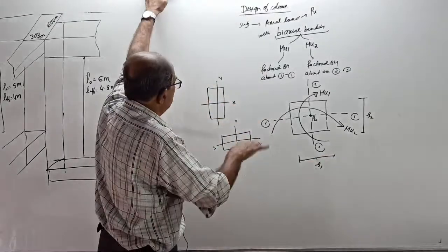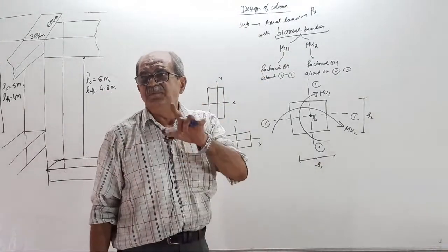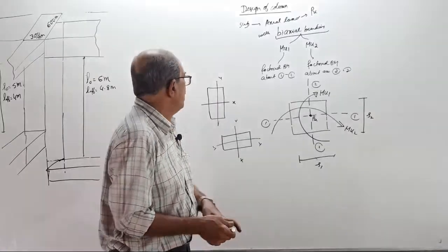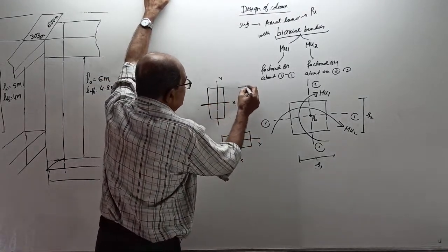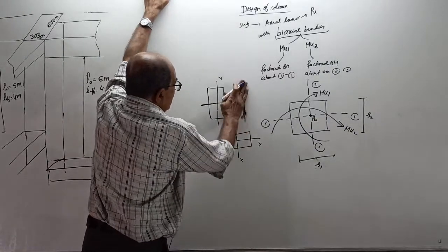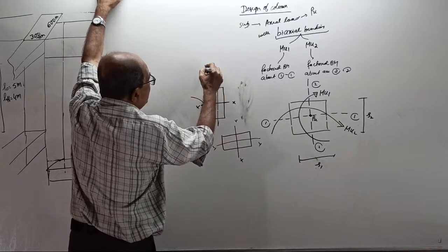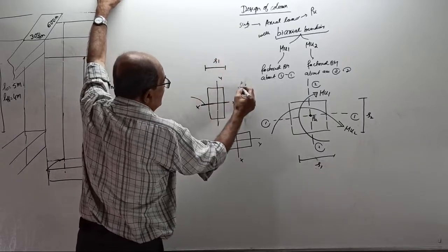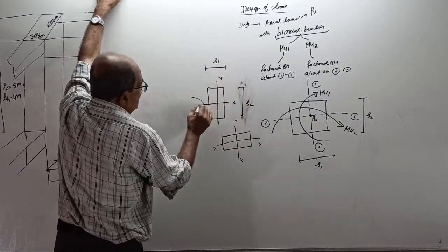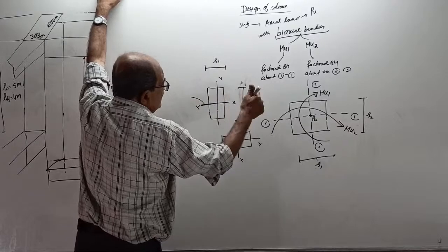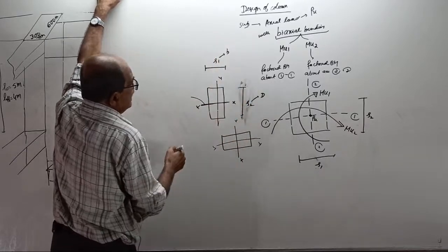Okay, start, continue. Now, when depth is more, then the section is stronger. Therefore, remember, with respect to the x-axis, this is the depth. For this cross section, if I take this way S1, this way S2, then S2 is more than S1. With respect to x, your S2 will become depth and S1 will become breadth.